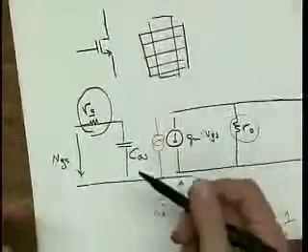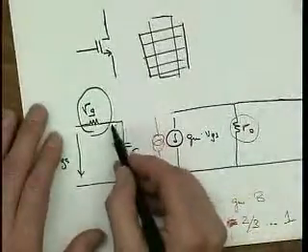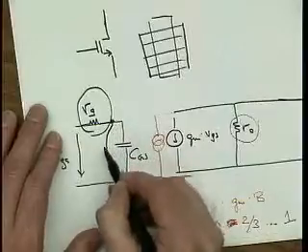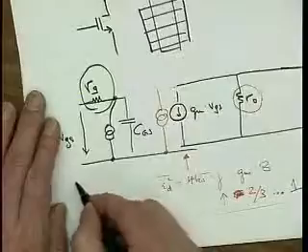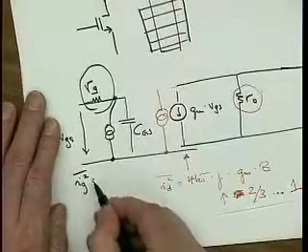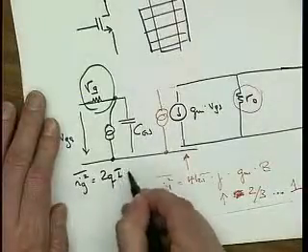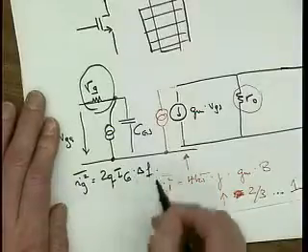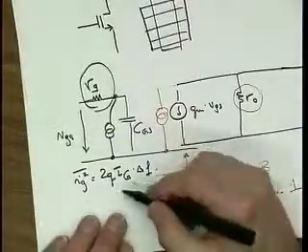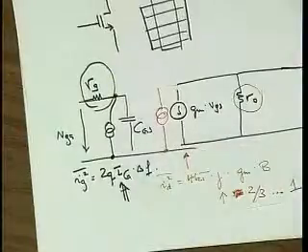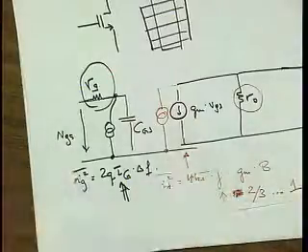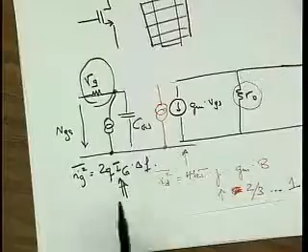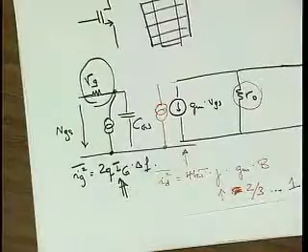Okay, yeah. So of course, if our FET had a gate current, then we would have IG squared would be 2qIG delta F, right? And we would have this in addition. Fortunately, up to now, this gate current still is, forget it. Maybe 5 years from now, that will no longer be true, and we will have an extra bloody noise source to deal with. Huh?